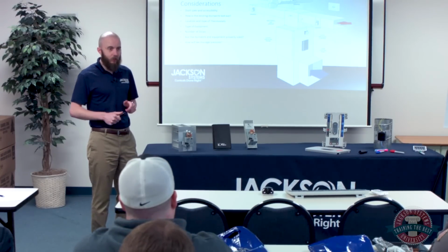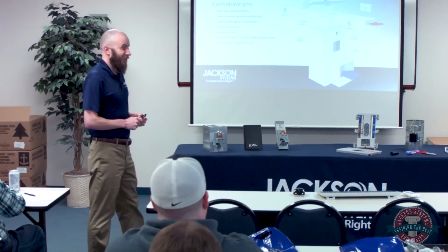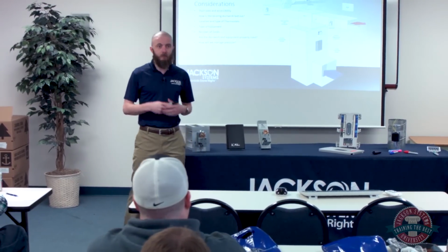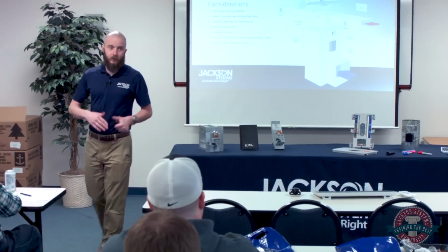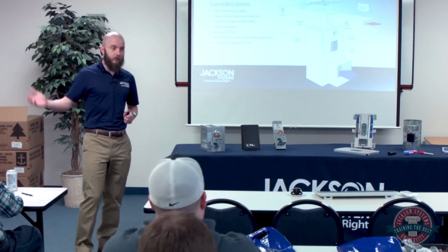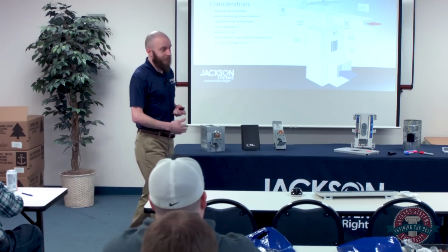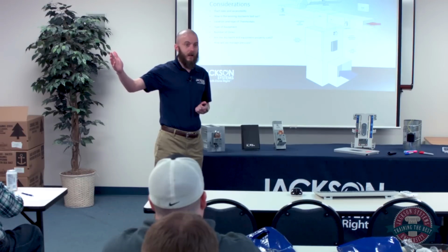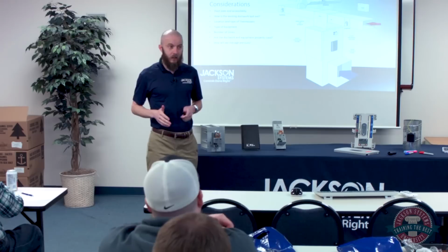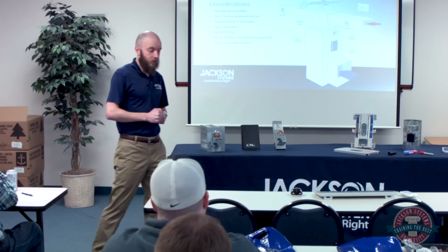Even if it was sized properly and the equipment was sized properly once upon a time, that's not to say nothing's changed in the house since that equipment was sized. If they do a remodel, finish a basement and whatnot, suddenly you're conditioning a lot more space than it was originally designed to, and no one ever upgraded the equipment, right? If that equipment ever got replaced, a lot of times somebody's going to go out and say, oh, you got a 4-ton system, I'll replace it with another 4-ton system, and never bothered to check whether it was sized right to begin with or whether anything's changed since then.